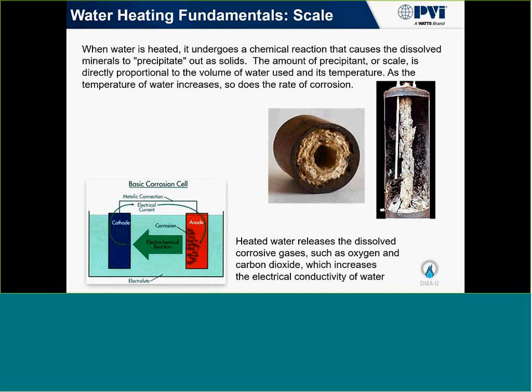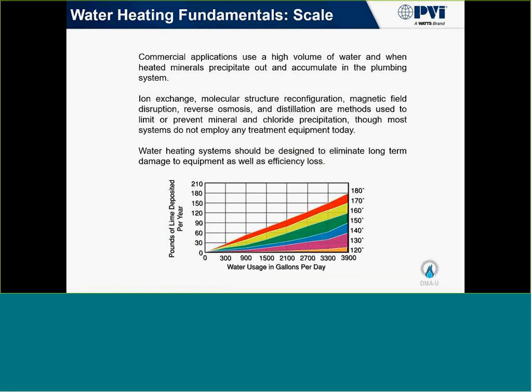So what that's also going to do is make the water more conductive, more aggressive, and as a byproduct, it's going to push oxygen and carbon dioxide out of the water into the rest of the system, which is a natural byproduct of that reaction. So with scale, we all deal with it. Scale's prevalent in almost every situation we come into. And there's a few different ways that we can combat it.